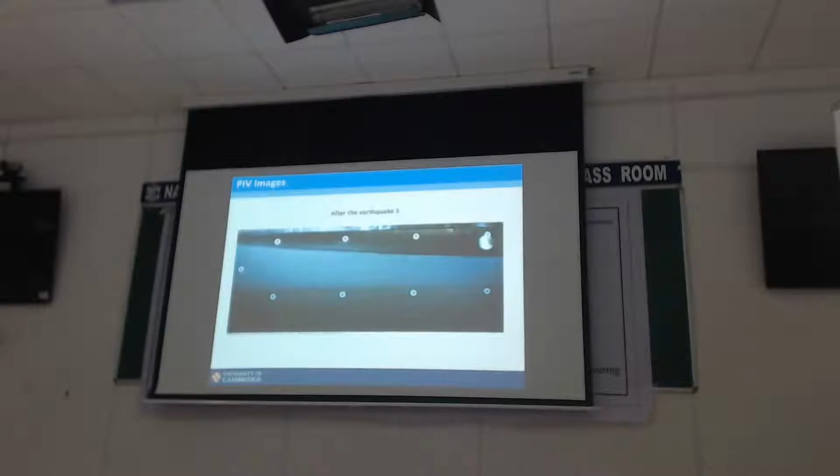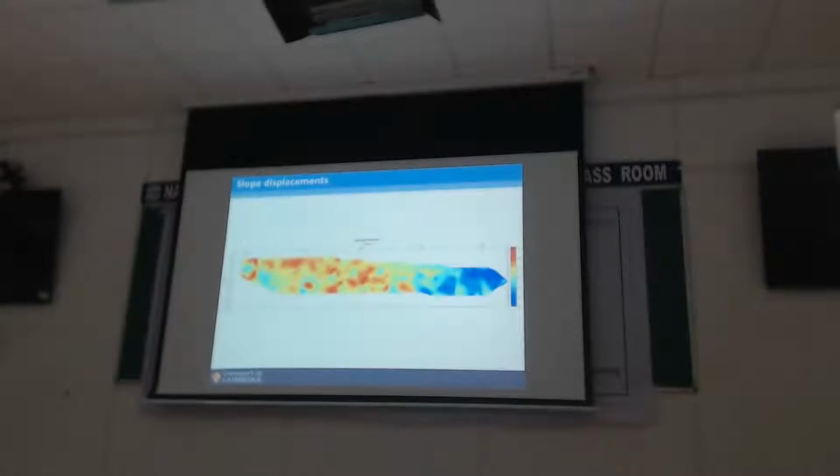Hardly any movement, like what we have seen. And if I now plot the displacement vectors, where before we were getting nice big things, you can hardly see the displacement. It's not going anywhere. That's the problem. It's too stiff. So if you do the test at 1G, the soil is too stiff, and therefore the deformations will be small.